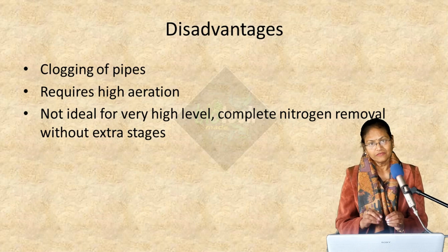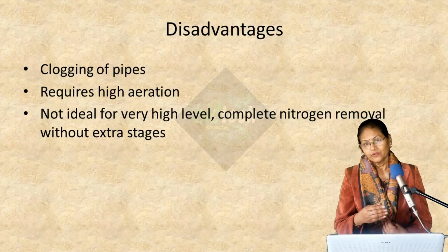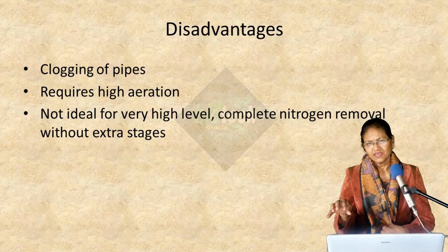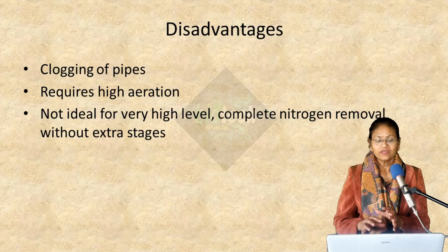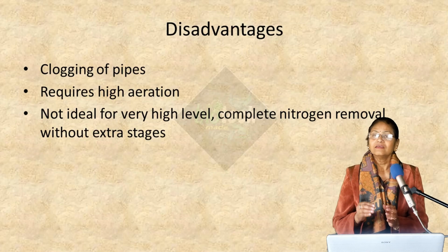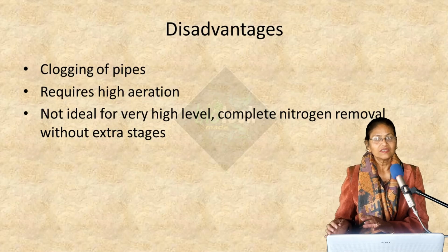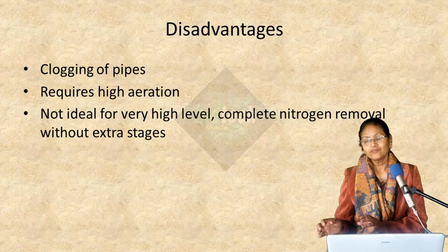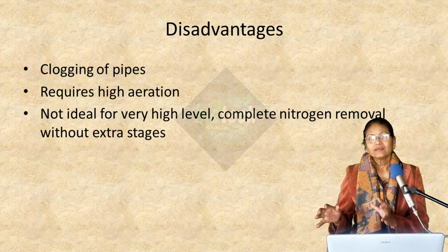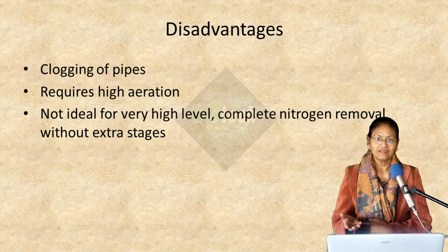Although nitrification and denitrification are both going on together, some nitrogen is removed, but if you want complete nitrogen removal, then extra stages are needed. Because aerobic and anaerobic conditions are different. The microorganisms that have to do the denitrification have to live in completely anaerobic conditions, so extra stages are needed.